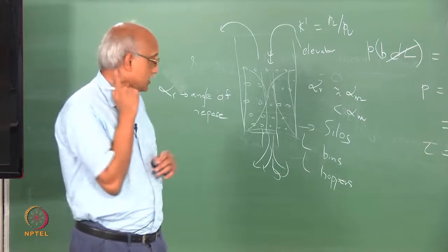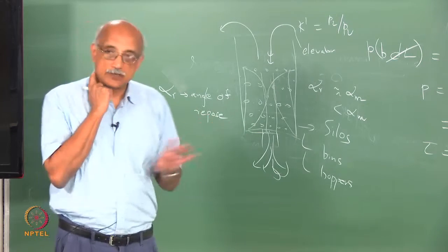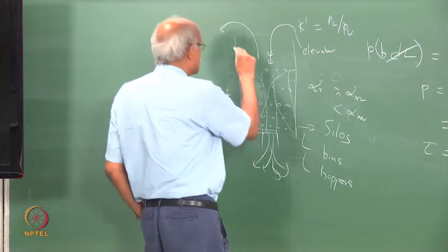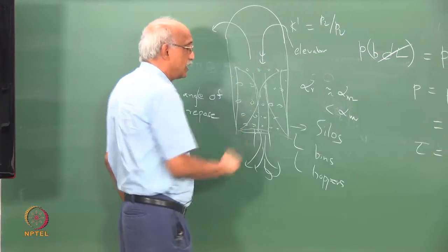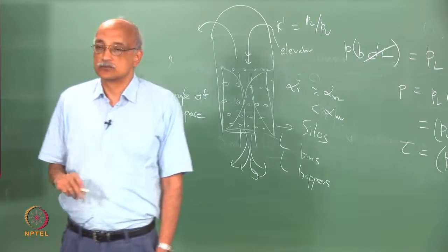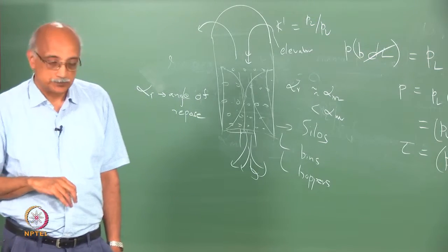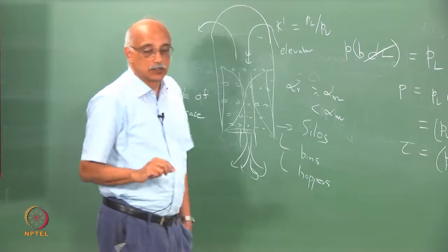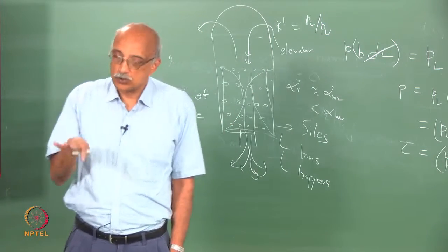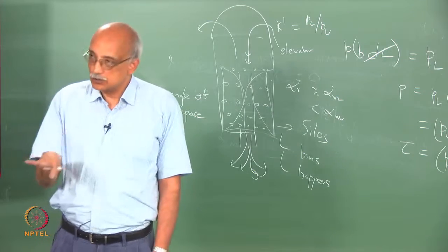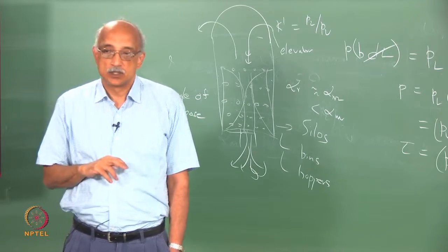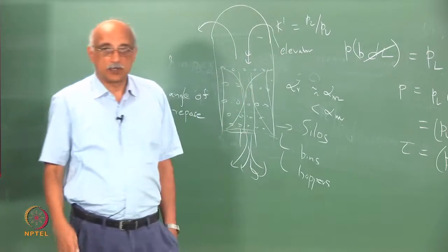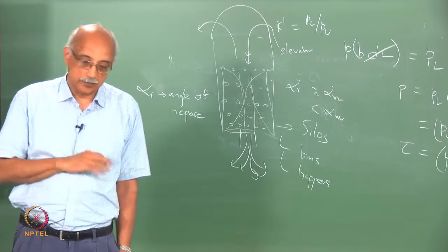very rapidly. So, environmental controls are very important, and typically what they will do is put a cap on top of the bin or silo, and this will be sealed, so that you can control temperature and humidity inside this silo. The only time you open it is for charging, and then you immediately close it again.